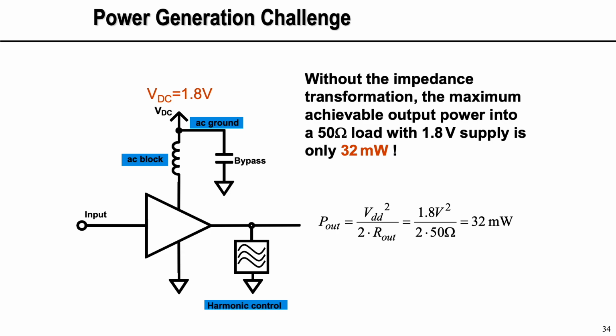So if I were to just take this amplifier and make it like a standard analog amplifier, like the output stages that we drove, and even if you allow it to go above VDD by a factor of 2, by biasing it with an inductor in the middle and letting it go above and below, the maximum voltage swing that you will have is from 0 to 3.6 volts, roughly, first order. And the amplitude is going to be 1.8 volts for that sinusoid that goes from 0 to 3.6. The amplitude is 1.8 volts.